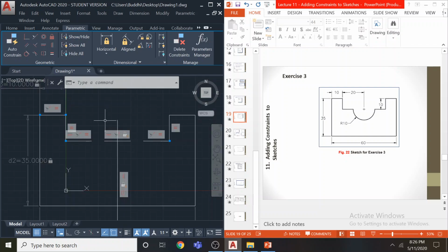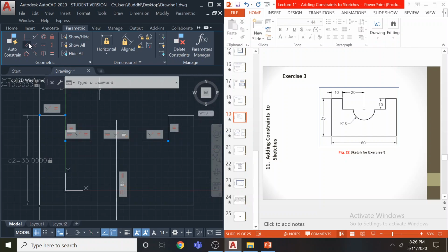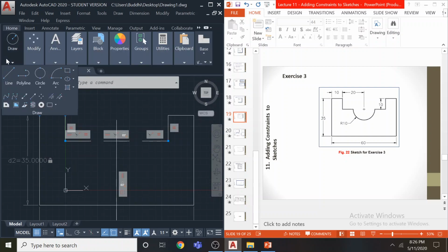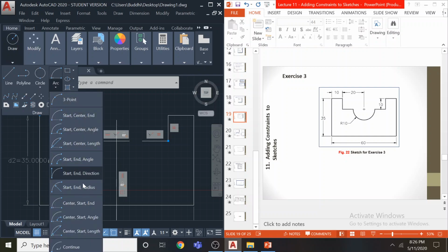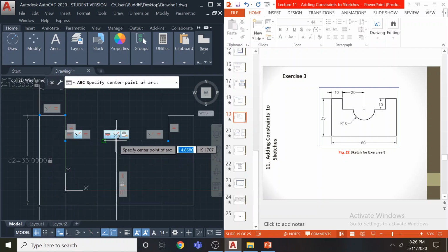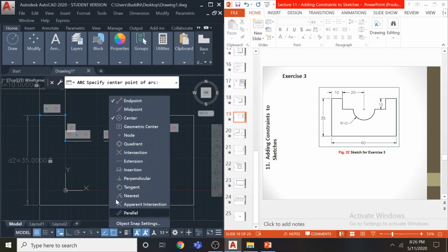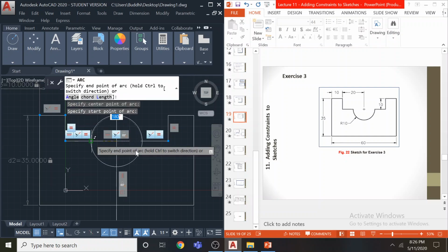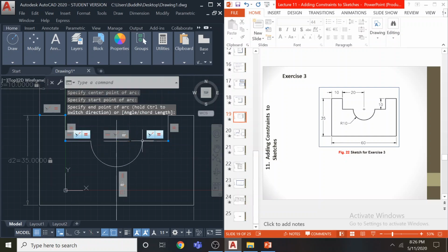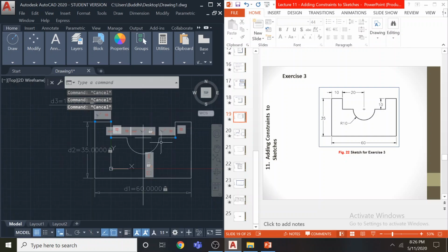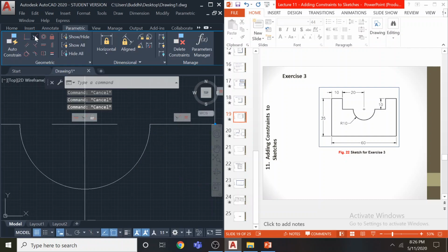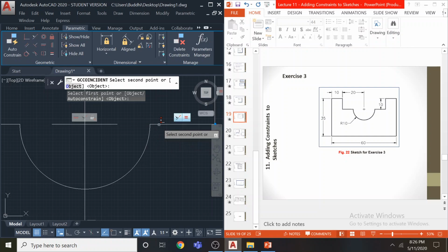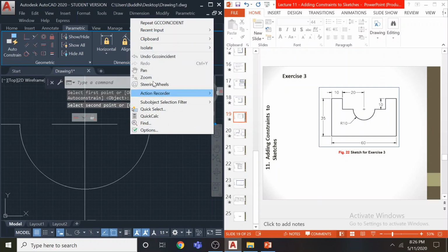Now we can use the arc tools. I'm going to use the arc tool called center start end. Center is now clearly defined. Say I'll just give the intersection center, starting, ending. Make sure you apply coincident symbols. Coincidence relations. Done.